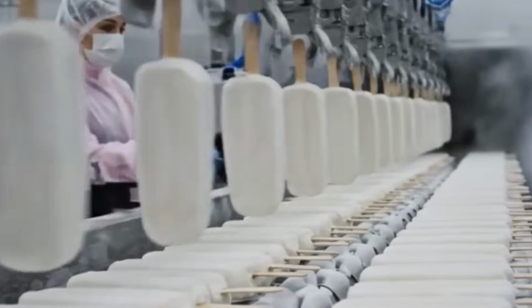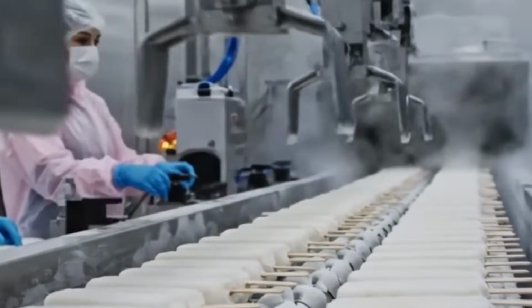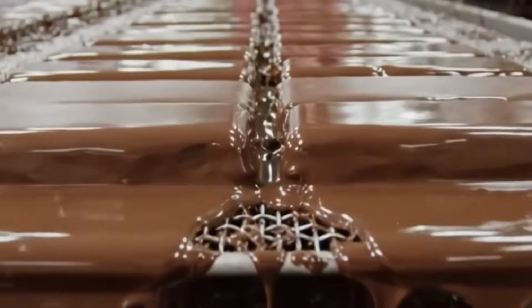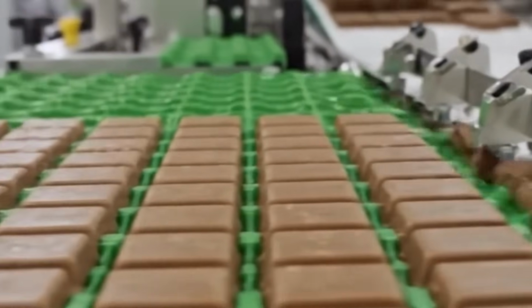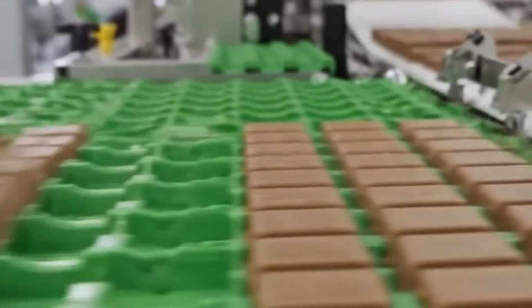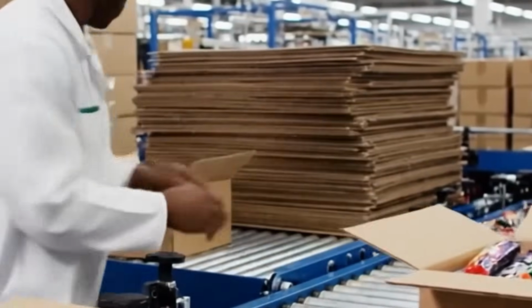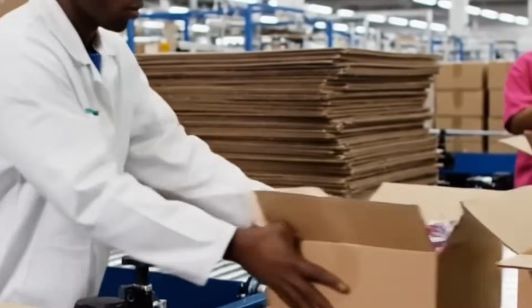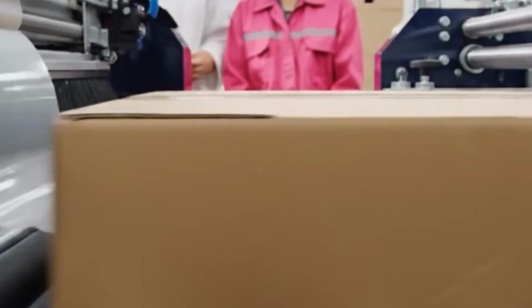The belt carries the formed shapes under a quick freeze chamber where additional cold air is blown to firm up the shape. Inline sensors monitor form consistency and weight. Shapes are cut by ultrasonic or wire blades synchronized with belt movement.